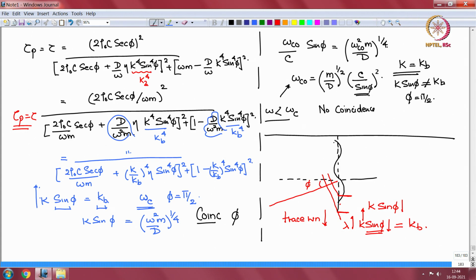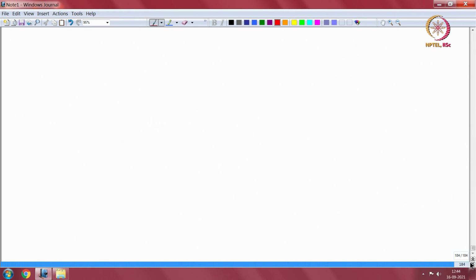We are talking so much because there are these terms where you have 1 minus the ratio of forced to free wave numbers. In another way, if we have a free acoustic wave number line here, and this is my kb, the panel free wave number line over here, then let us say I have a certain angle at which I am incident.